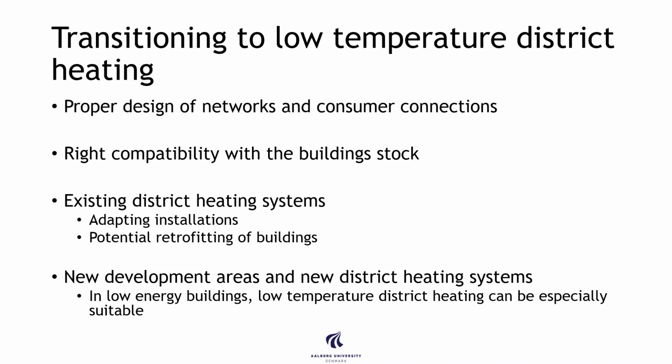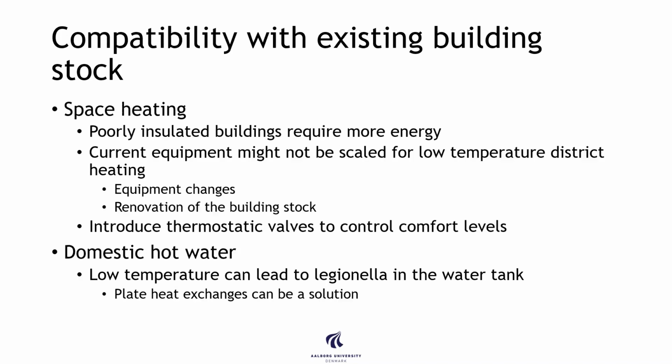Also, one of the issues that some people mention is that district heating is not viable in a low temperature building or in a new low energy building, because we don't need so much heating. But this can actually be made more relevant with low temperature district heating, because then the whole system is scaled better to new design standards for low energy buildings. And this is also what Brian mentions, that there's a lot of synergy between energy efficiency and district heating.